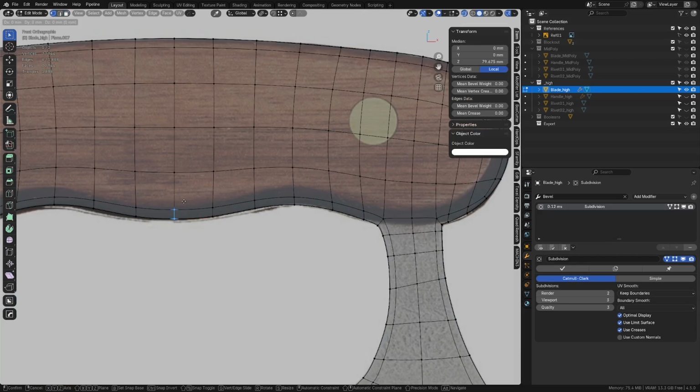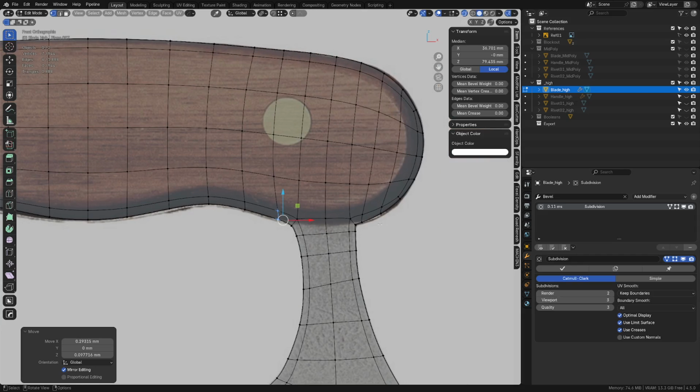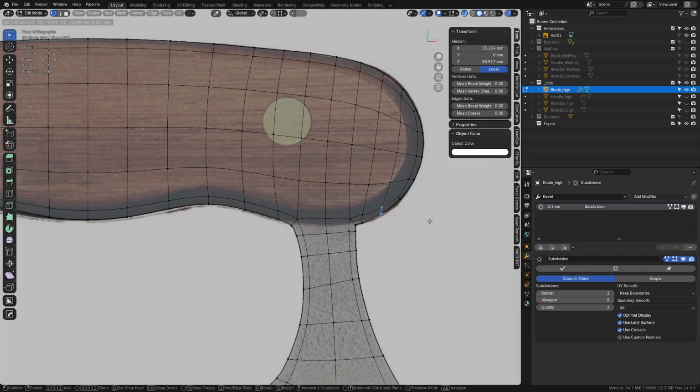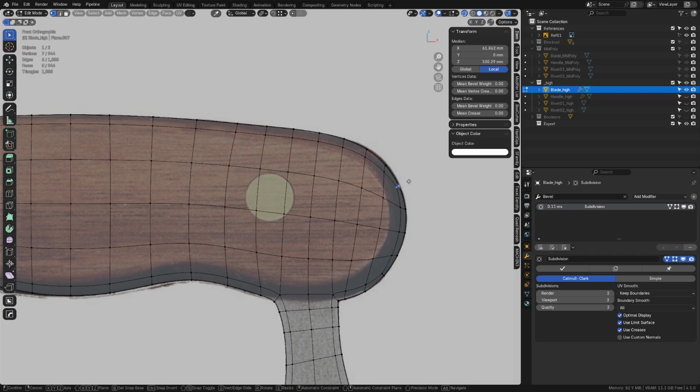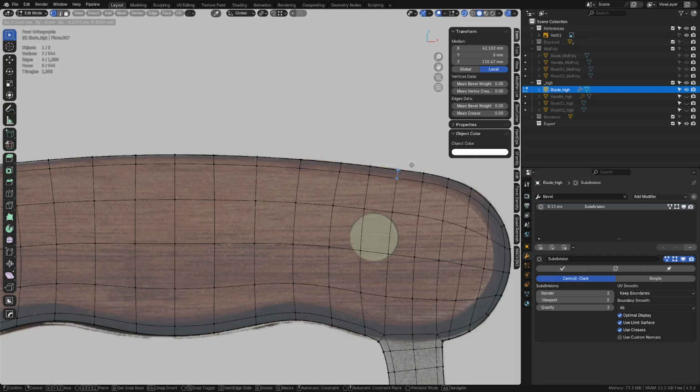And remember, when you're creating a subdivision model, your actual model that you're working on is not the cage or the control mesh. The subdivision result, when you actually apply the subdivision, that is the model, right? That's the model you're creating. So you turn on end result sometimes, and you can go through and check it and tweak it and adjust it. Because you can see we're close to matching the image. It doesn't have to be perfect necessarily, but oftentimes it can be very useful to go back through and just very carefully tweak things.